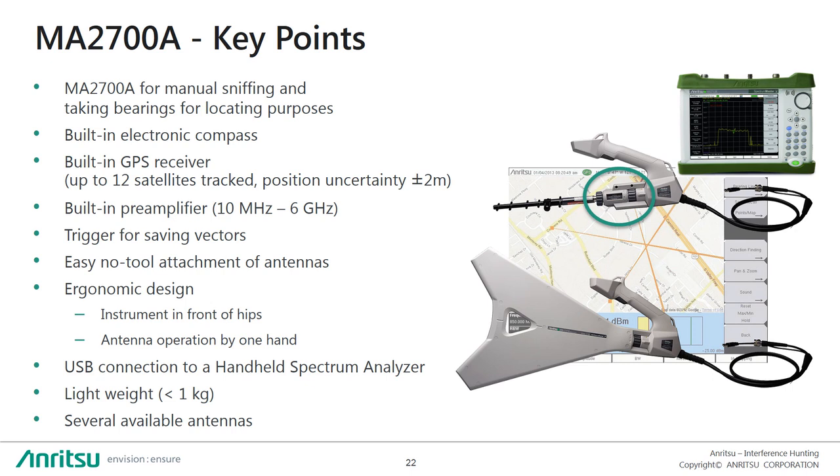Now, once you're done with the Mobile Interference Hunter, you have a pretty good idea of where your interfering signal is coming from. In order to be able to tell with even greater precision, you will need to get out of the car and do more traditional direction finding. And more importantly, the Mobile Interference Hunter will indicate where the channel power is highest at street level. If the signal is coming from a tall building, you will need a directional antenna in order to pinpoint its source.